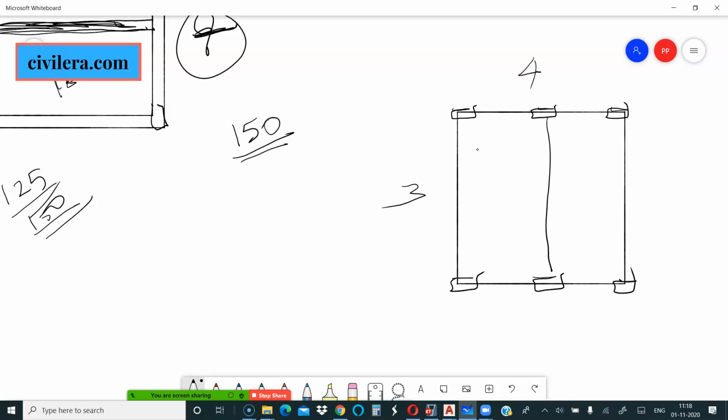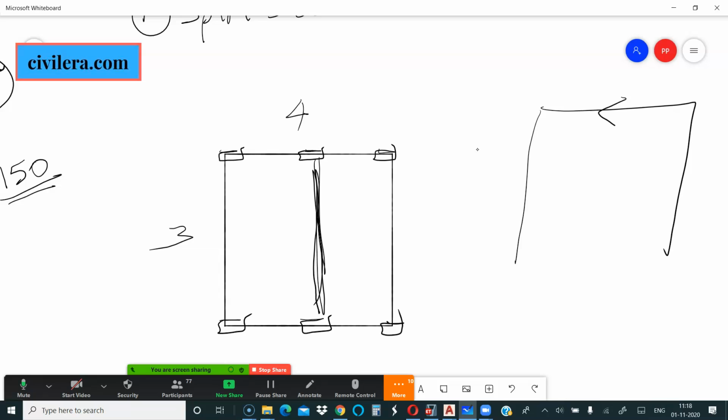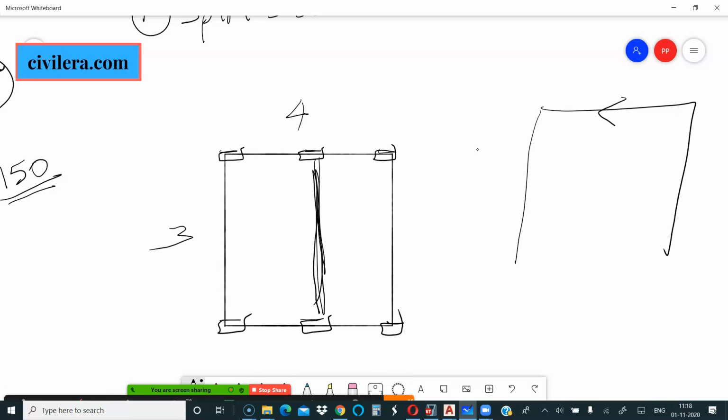You cannot leave the columns untied for 20 floors. It will be really slender and it will be swaying. Basically what this tie is doing is giving a tie action. When the column sways in one particular direction, the beam acts as a compression or tension member and pushes or pulls it back. So here, if the sway is in this direction, it's being pushed or laterally restrained by that beam as a tie. Also, it helps you to transfer the load throughout. That's all what I mean by the tie action. Same way, if it is swaying in this direction, it is being pulled by that beam.